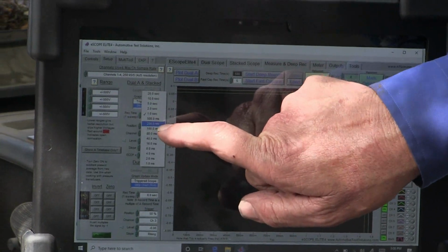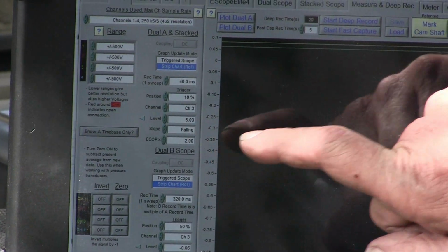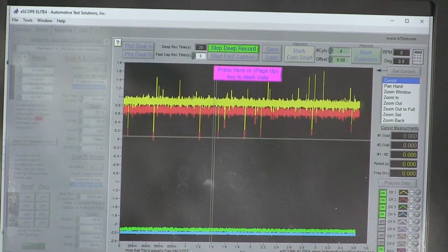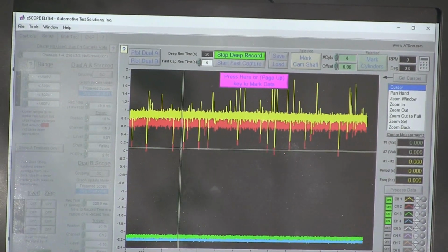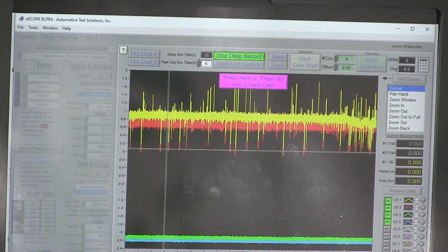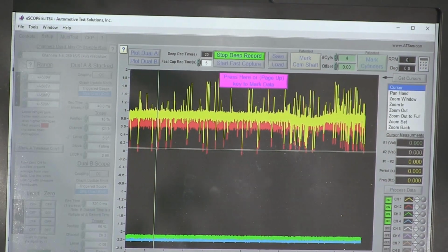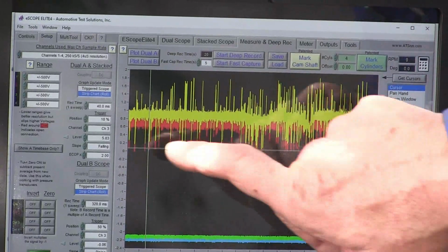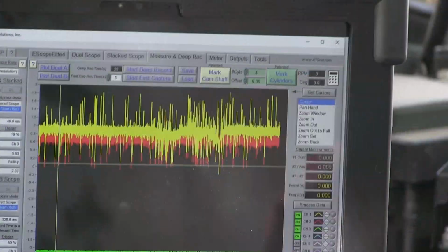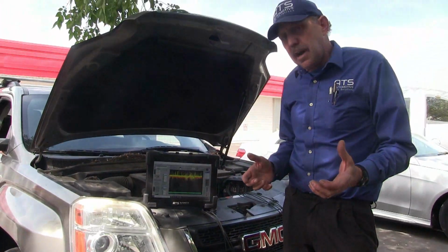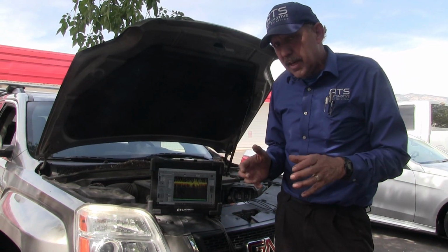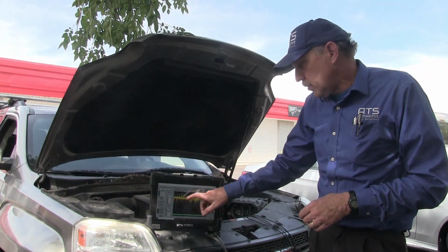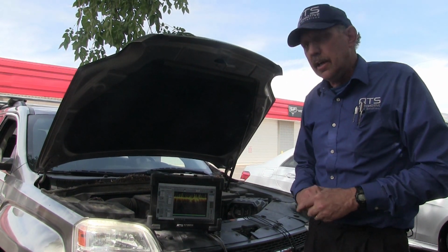I want more time. So now we have 20 seconds of time, and we're recording those 2 traces. So let's give them a couple of hits with the throttle. Now that should have made that O2 sensor go high. And we can clearly see the O2 just isn't working correctly. So this O2 has some type of a problem, but the most important thing is, why is my bias voltage low? Because this should be higher. So this O2 sensor definitely isn't working correctly.